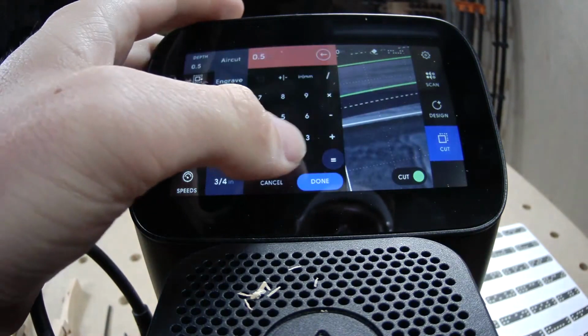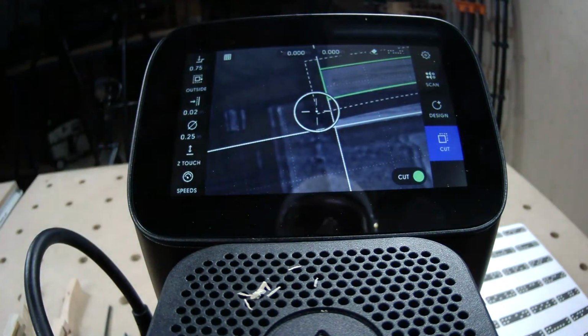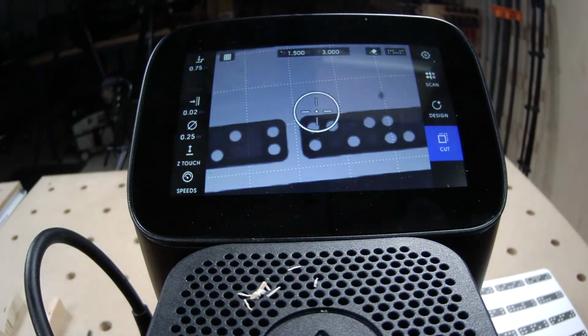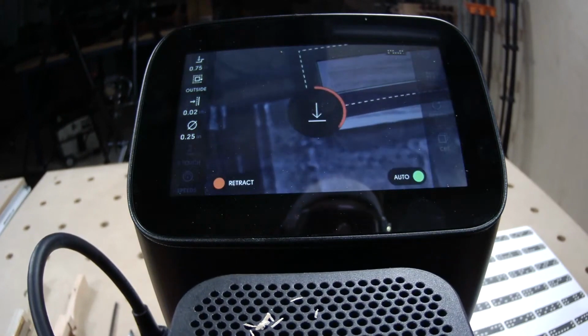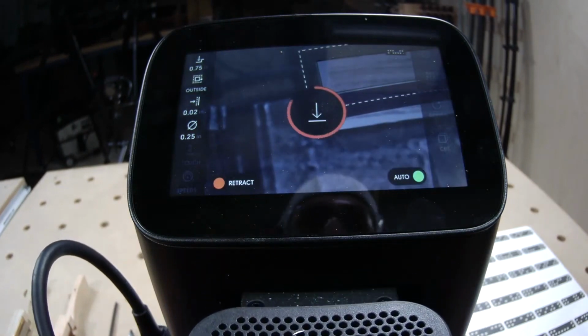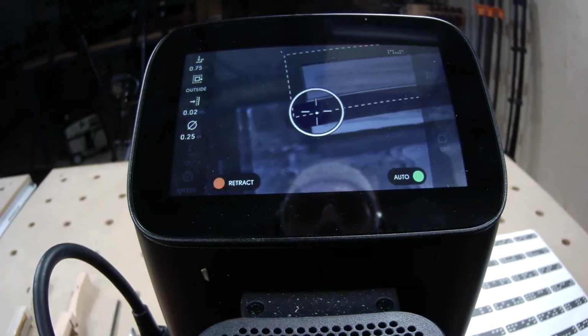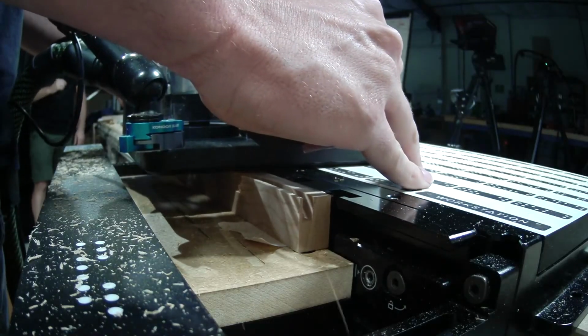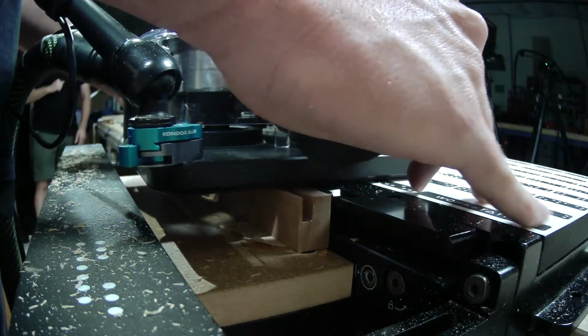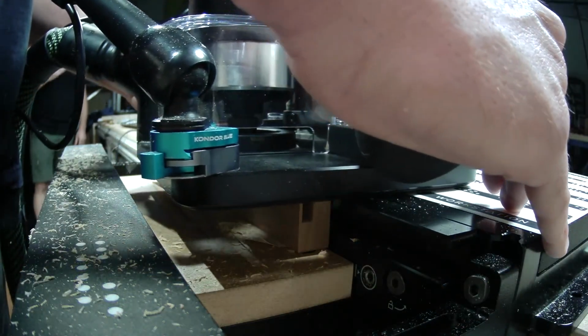So even though he's got a short cutting flute that technically wouldn't let him cut to the full depth in one direct straight down session of multiple depths, he can do it by adding a little offset as he goes. And that just gives him enough breathing room for the area that's not cutting to clear, make it through without causing friction and burning.